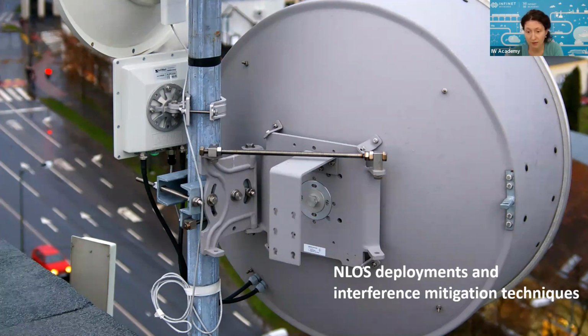Then we are asked if InfiPlanar is effective on non-line of sight links. If you have a complete non-line of sight link, it will not predict anything. It will just say 0. If you have near line of sight, it will tell you how much of the Fresnel zone is obstructed and what you can obtain, but only for near line of sight. If it is completely obstructed, it will return 0. It will not plan the link.